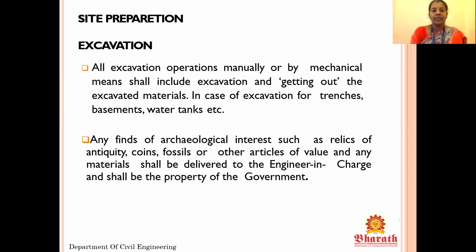After preparing the job layout, we can go for site preparation. In that we can see about excavation. All excavation operations, manually or by mechanical means, shall include excavation and getting out the excavated materials, in the case of excavation for trenches, basements, water tanks, etc. So excavation operations should be done either manually, if the construction work is very small in size, or otherwise we have to depend on mechanical means.